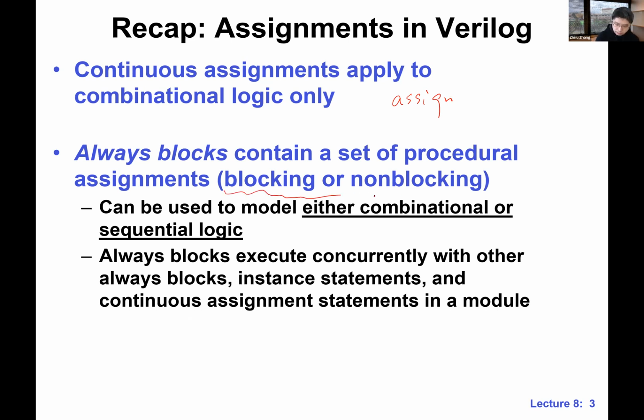I'm going to talk a little bit more about blocking and non-blocking assignment later on. Okay. But just want to make sure that when you write these Verilog statements, whether it's an instance statement, where you can instantiate new modules and build things hierarchically, or a continuous assignment, or these always blocks, you can write them in any order that you want, as long as they are readable. But really, you're actually modeling concurrent hardware. So this is really something that you need to pay attention to.